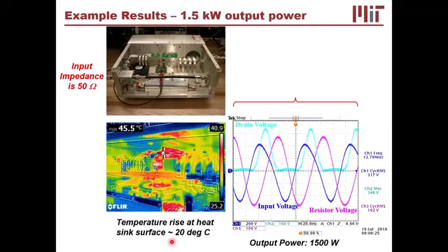So this is the kind of thing you do, and we used exactly these models to figure out the thermal resistance from the junction to the case. Then we had the case going down to the heat spreader, and it was soldered, so that's pretty low, and the heat spreader to the heat sink, and the heat sink to ambient, we looked up from the data sheet, and boom, we have our model, and we can pour lots of dissipated power into it and still keep it cool.